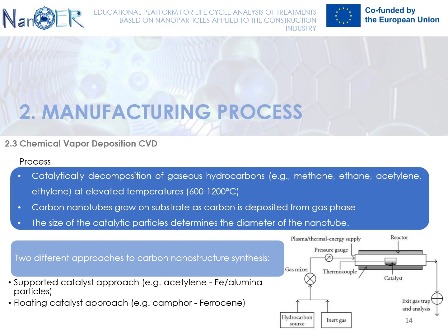The catalyst is placed inside a ceramic mold at the center of the furnace, according to the supported catalyst approach. The whole process takes place under oxygen-free conditions by flushing the system with an inert gas. Simultaneously, the furnace is heated to a desired temperature until a steady state condition is achieved. After the stabilization, the gas flow for acetylene along with hydrogen is released for a desired time of reaction. After the end of the process, the CNTs produced are collected and weighed.